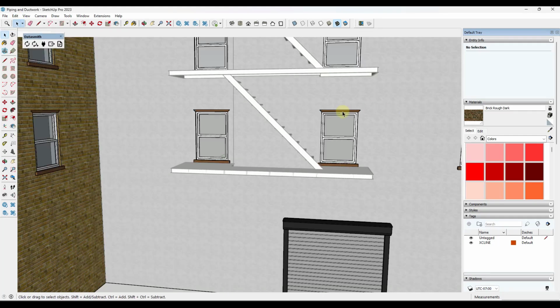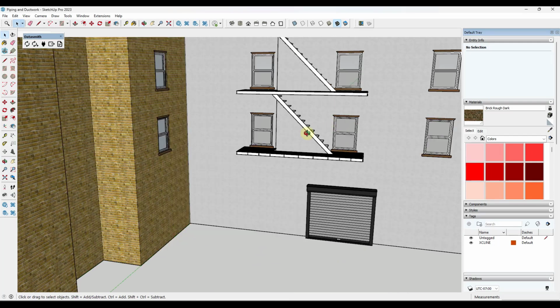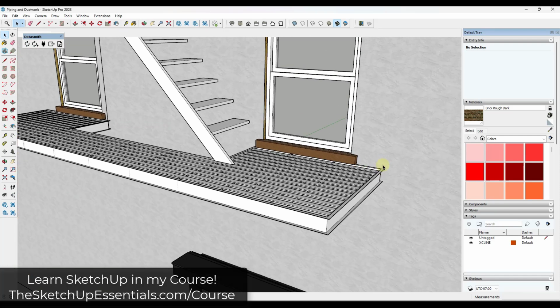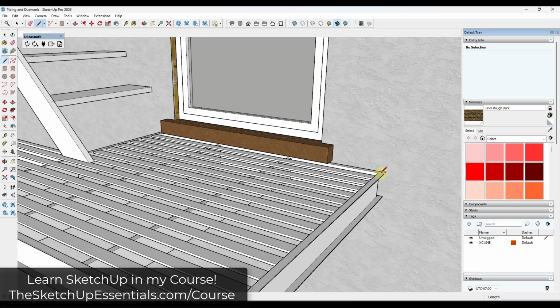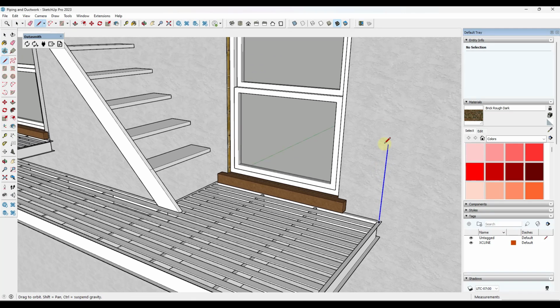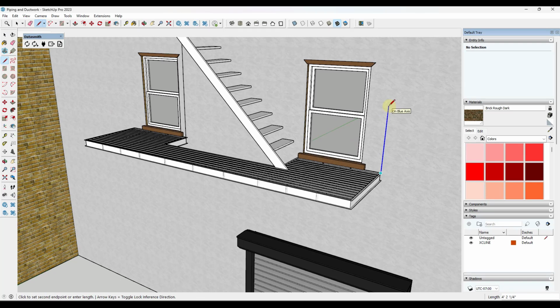In order to get our stairs back. So now all we need to do is add our rails. And so you can make these rails as simple or as complicated as you want to. In this case, I'm just assuming they're going to have some kind of a steel tube in here. But I'm going to go ahead and draw a line up to whatever the height of that rail needs to be. I guess we can assume maybe 4 feet.